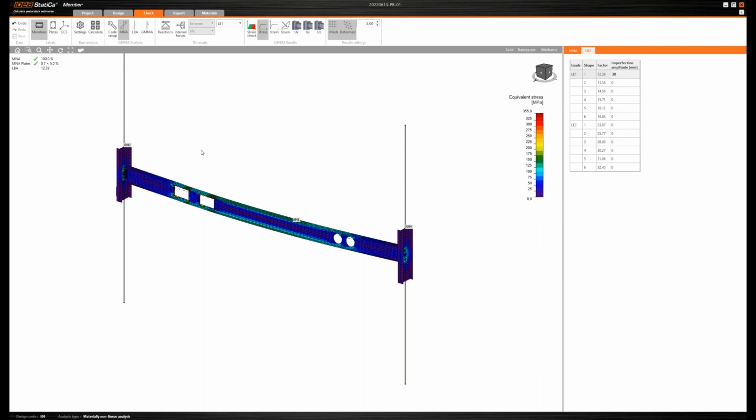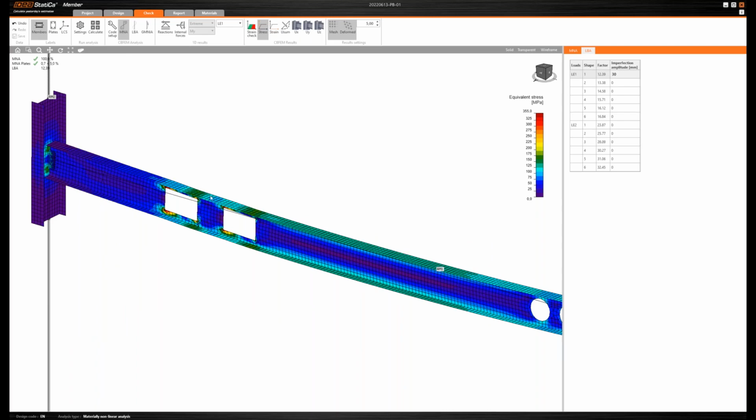Okay. Can you model point moments on the beams? Again, like I said, even the point load here needs to have some dimension due to the underlying shell model. So a point moment will be a triangular load with dimensions in order to avoid the stress peaks. We do not want to have stress peaks on our models.